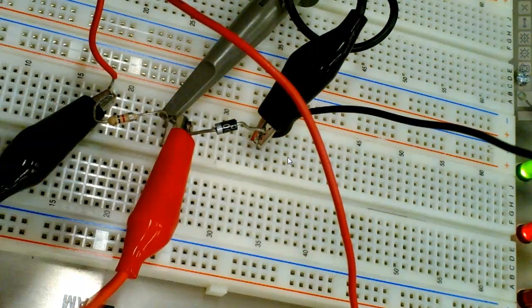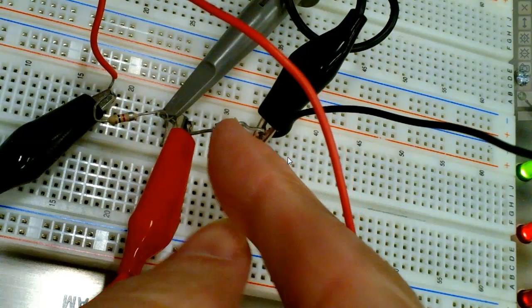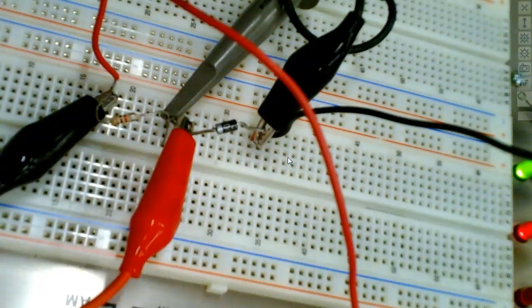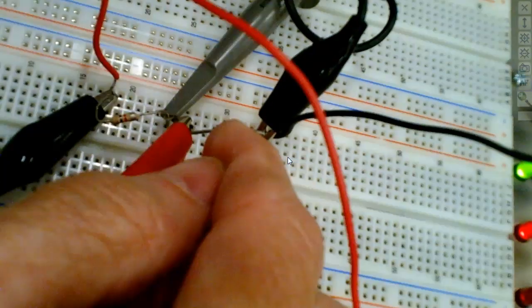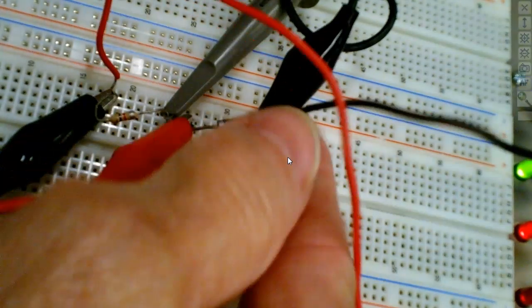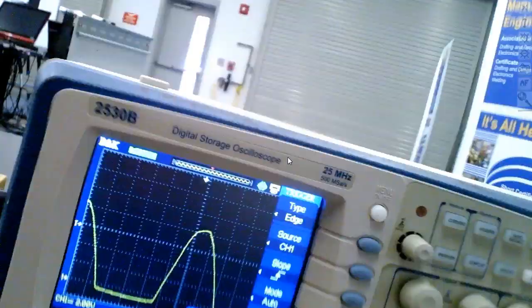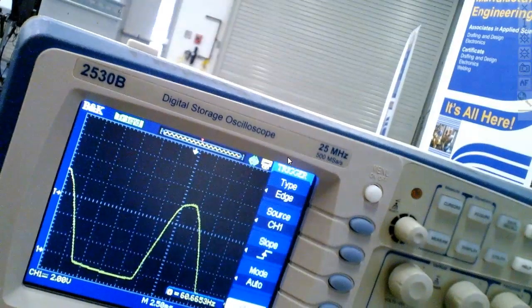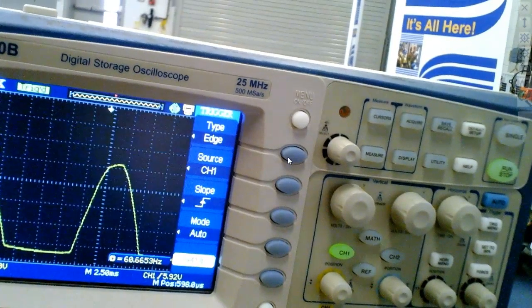So what happens is now I've got a positive supply because I've got my anode. To determine if it's a positive supply or a negative supply, you look and see which is pointing toward the source. Here the anode is pointing toward the source, so that means this right here is a positive supply. If I come over here and look at my waveform, it looks a lot better now because I'm using the right common back up. I was using the common on this, and it's isolated.